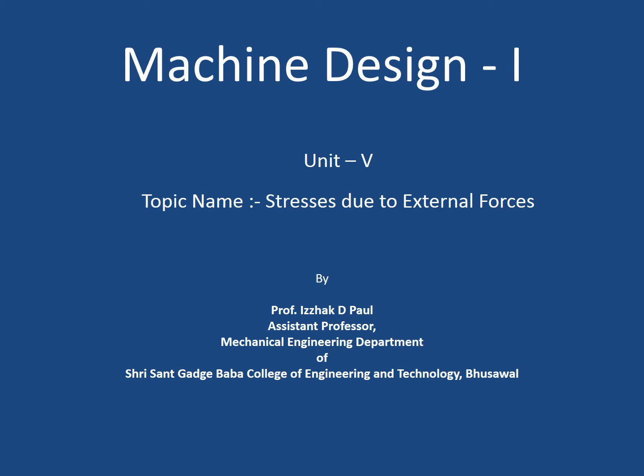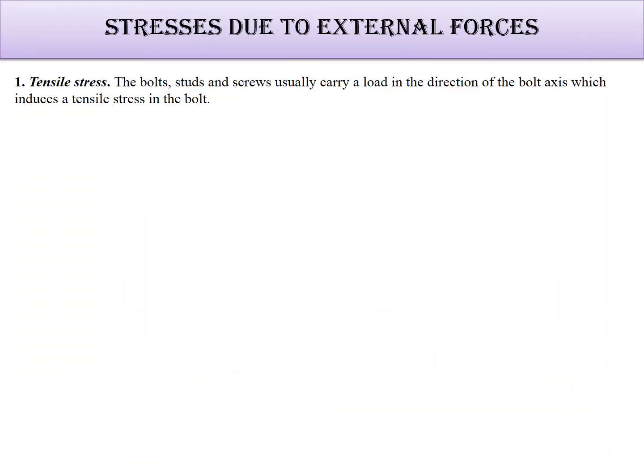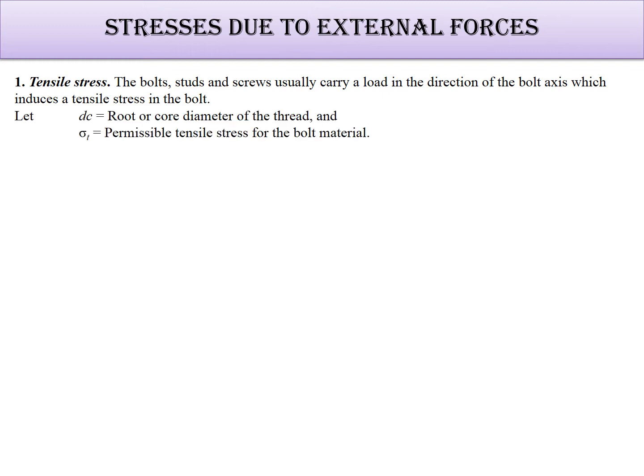So this is the next topic. We have seen stresses in screw threads. Now, stresses due to external forces on this. Here, first the tensile stress, which we have seen. The bolt, stud and screw usually carry a load in the direction of the bolt axis. So due to this, tensile loads are there.